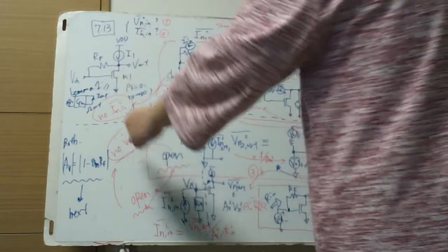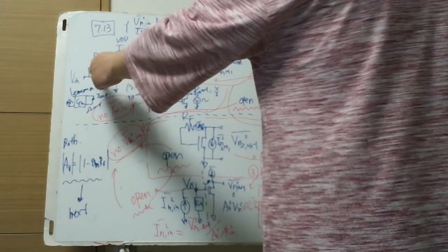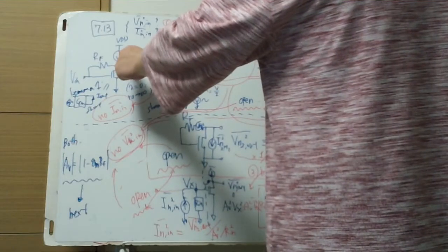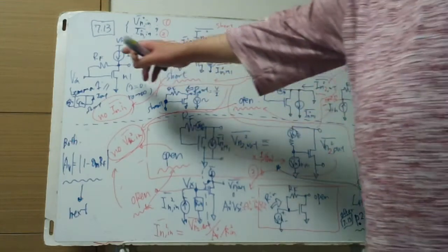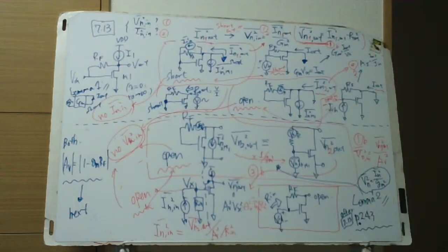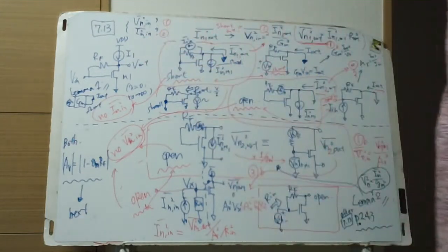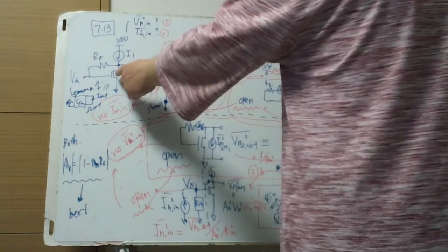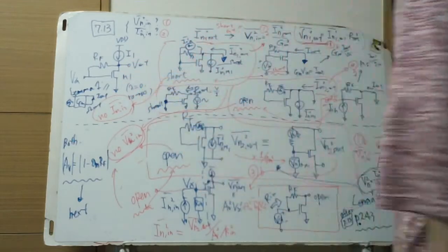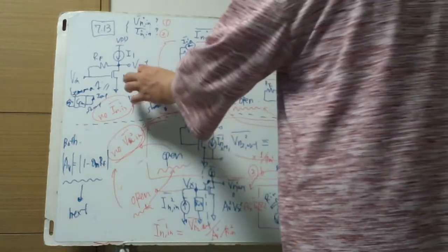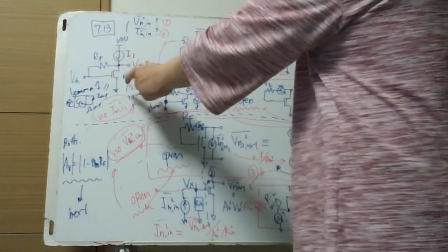The problem is a common source amplifier having feedback from output to Vin, with a resistor value RF, and I1 is constant with no noise, and lambda equals 0, which means the NMOS M1's ro goes to infinity and is neglected when considering the R out, in parallel with RF and RO.